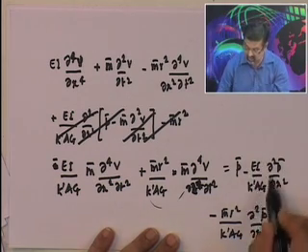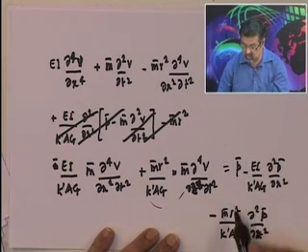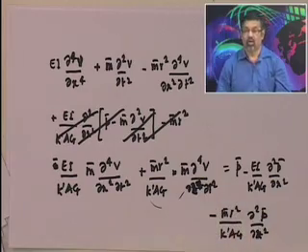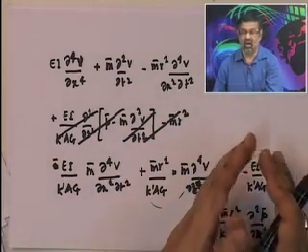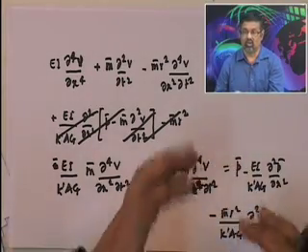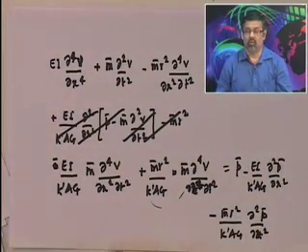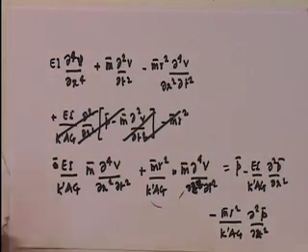Both of them are distance squared, and therefore, the right hand side is nothing but a load term. The solution of this equation becomes that much more complicated, but nonetheless this represents an equation of motion where shear distortion and rotatory inertia are included.